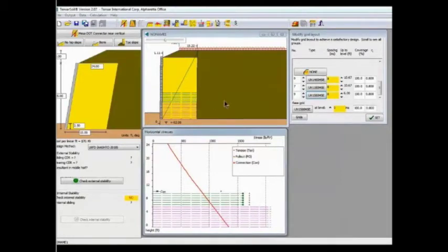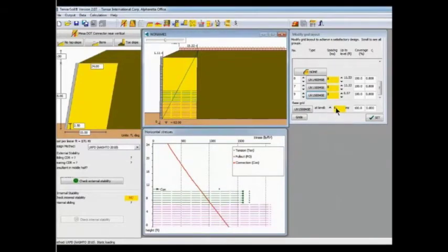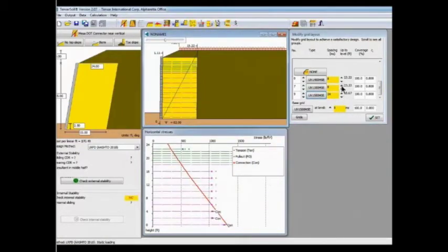So now we will change the geogrid to optimize it for the design. The software tried to maintain the spacing as best it could, but it dropped it down to 8 inches from the 18 inches for the SierraScape system. So we'll make sure our base grid is set at the top of the first block at 8 inches. And now let's try the 24-inch spacing we use for the NCMA design method for the MESA system.